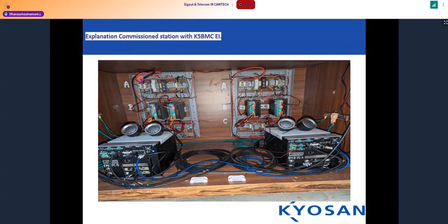From there, you will have an SPD. From the SPD, it will have a fuse. From the fuse, it goes to the terminals. From the terminals, 110 will be coming in the top, 24 will be coming in the bottom, and the 24 will connect to the PC. And on the PC, we will be installing a PCI card as I explained.